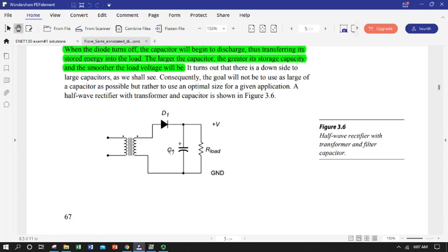So the capacitor is going to end up being oriented with its positive charge in the direction facing the upper half of the circuit. As the negative cycle comes out of our secondary, our input to our diode starts rolling back down towards zero. The capacitor, if it is fully charged, will now have a voltage equal to the peak coming out of the diode and hence from the secondary. So it will act as a voltage source, as long as it's got enough charge to keep supplying that, it will.